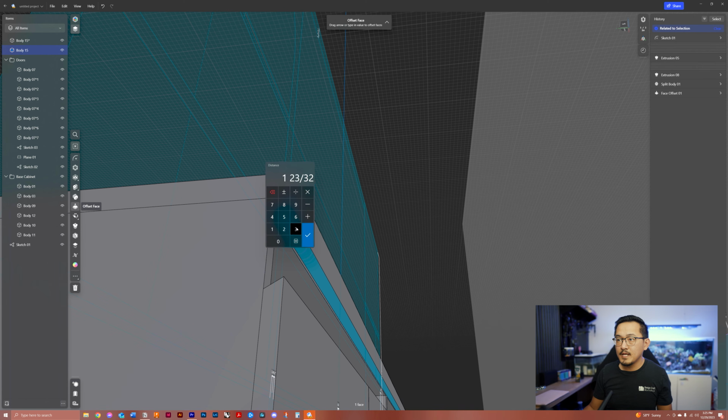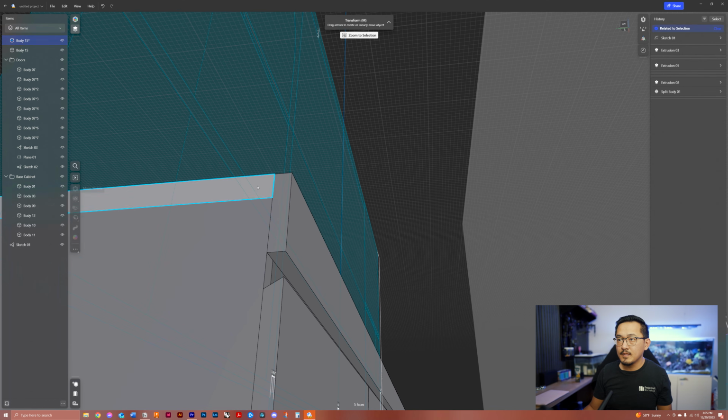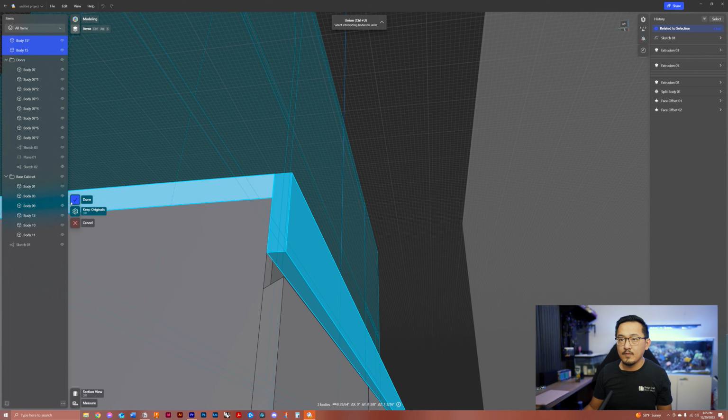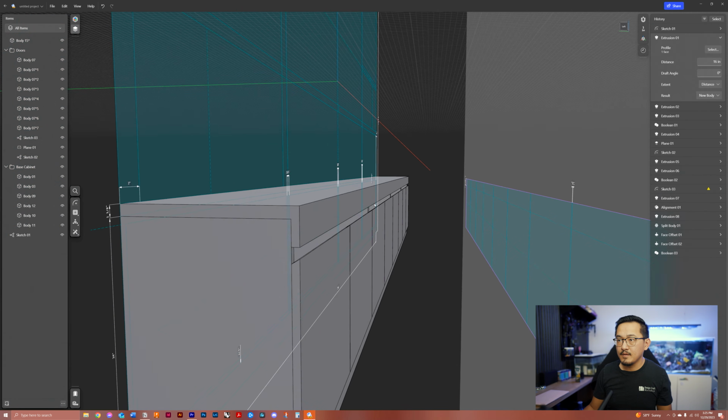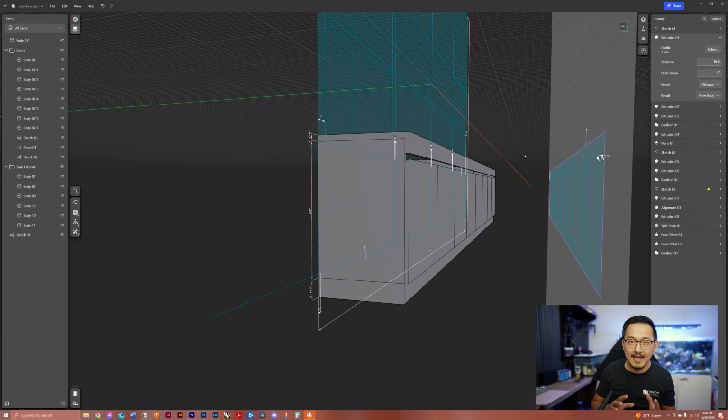So we're going to extrude this down to 3.5 inches, like so. And then we can choose to create a union for this if we want to, like so, there. And that is our countertop profile there. There's a lot of details, and if I were to draw this for a client, I probably wouldn't have done that profile and made it all complicated like that. I would probably just do the entire thickness and extrude that off of the sketch, and then worry about the measurement and details later when I actually go to build the project.